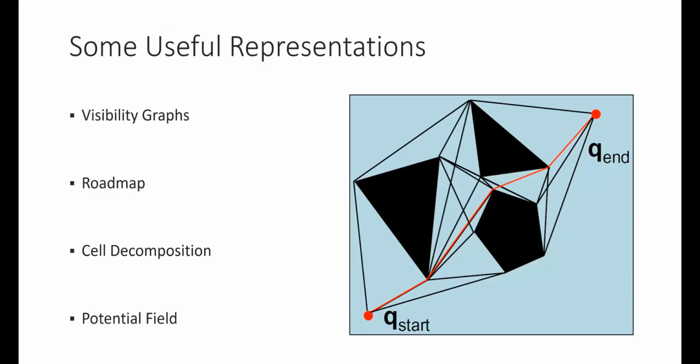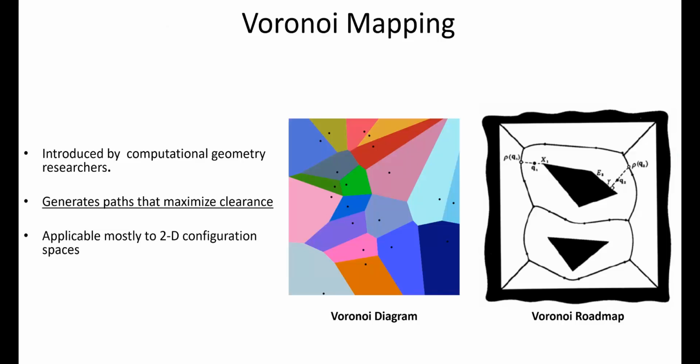And the Voronoi mapping that I mentioned before, the Voronoi path, here's a figure that illustrates how that comes out. So Voronoi paths are going to take an opposite approach, where I say, I don't want to actually be all that close to everything. In fact, I want to be really far away from everything. And so this approach will generate the path that maximizes my clearance between obstacles.